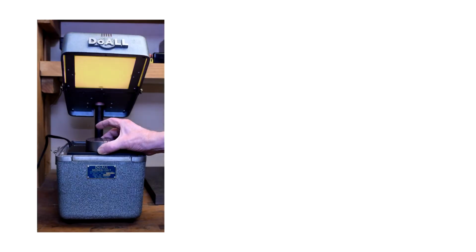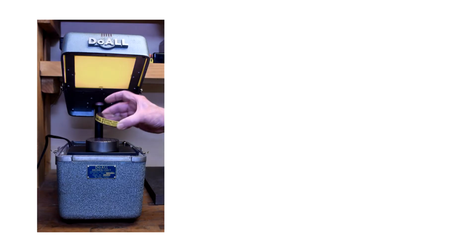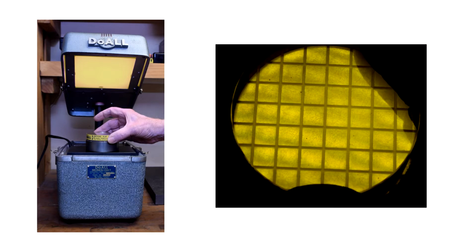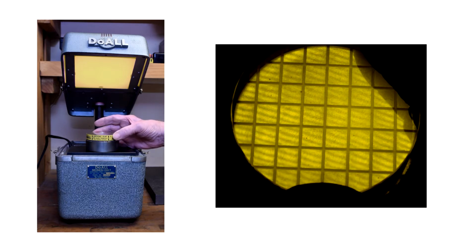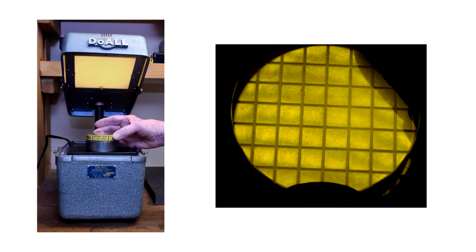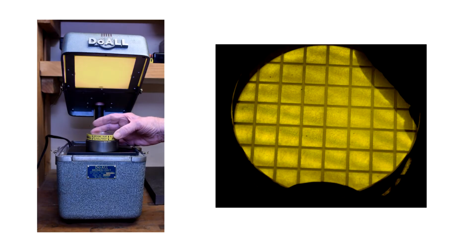Inspection with optical flats seems pretty straightforward. Just illuminate an optical flat placed over a part under inspection. Tweak things to get an interference fringe pattern, and read the surface contours by interpreting the fringe shapes. Say a gauge block surface looks like this. If it does, it's very flat. But if another gauge block looks like this, it's, well, not very flat.